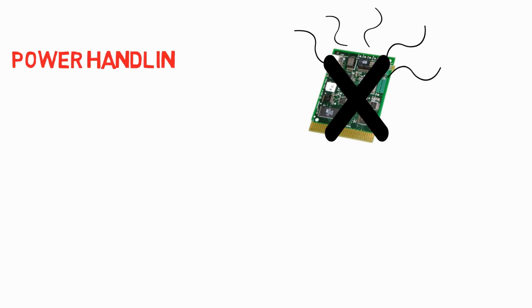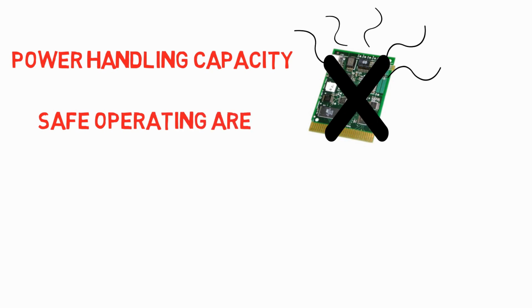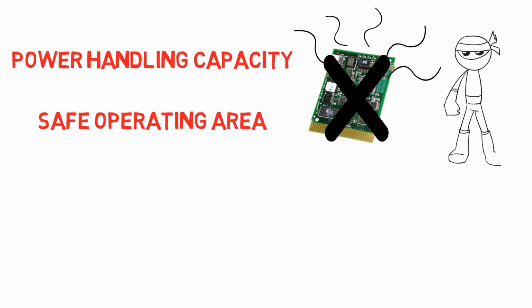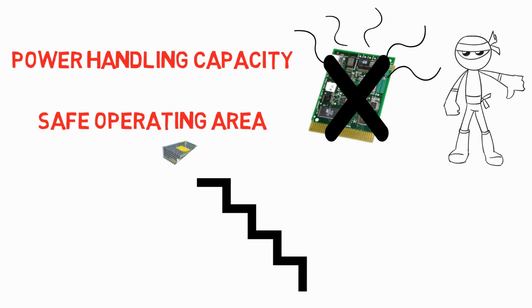If you do the power dissipation calculations of a circuit and you don't know the components, the power handling capacity or their safe operating area, then it will be of no use, right? For that reason, we must follow a specific order while designing, and the flow becomes much easier by determining the necessary information beforehand. Now let's go through a flowchart for designing of an SMPS.